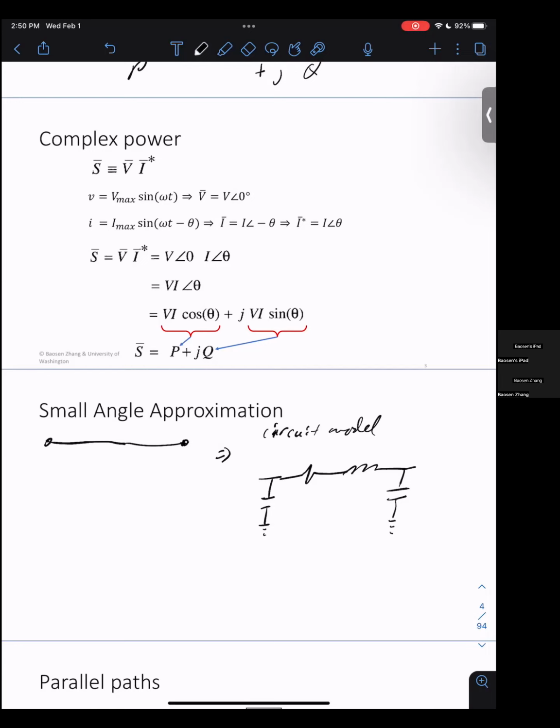If you solve the telegrapher's equation on this, because this is a power system, you very quickly get a standing wave, since there's no propagation of waves. Almost instantaneously you get a standing wave. It's as if the standing wave came out of a circuit like this. So it's not really a grounding effect. You just solve the telegrapher's differential equations, and the standing wave comes here. You can find these parameters based on the length of the line and so on. But this is a true circuit model.